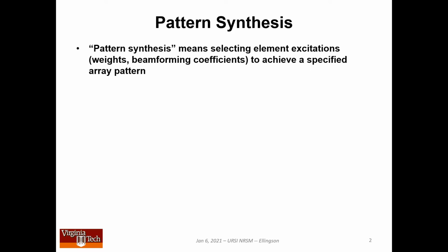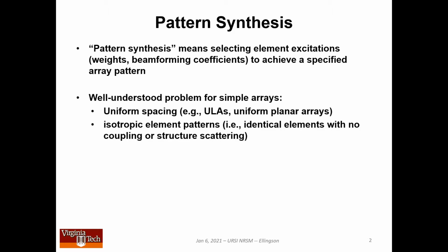Pattern synthesis means that you have an array and you're trying to find the excitations or the weights or the beamforming coefficients, however you'd like to refer to those quantities, that give you a specified pattern. This problem is very well understood for simple arrays. Any decent textbook will tell you how to obtain certain types of patterns given a simple array.